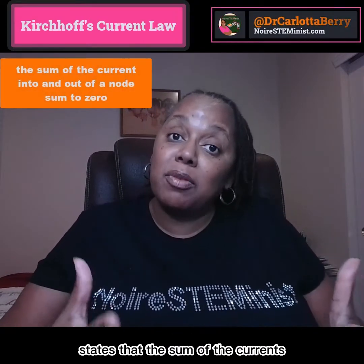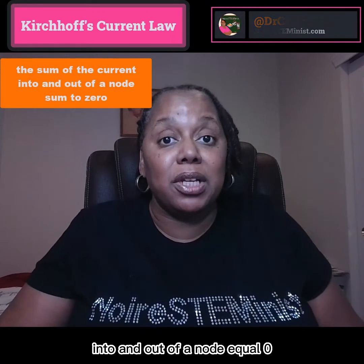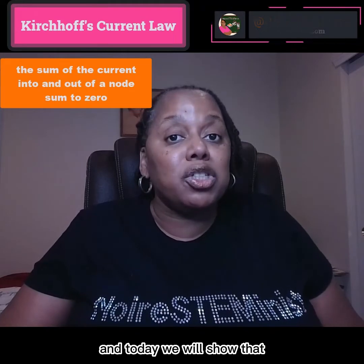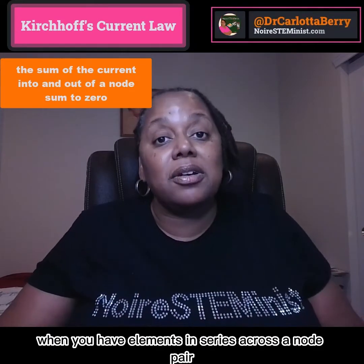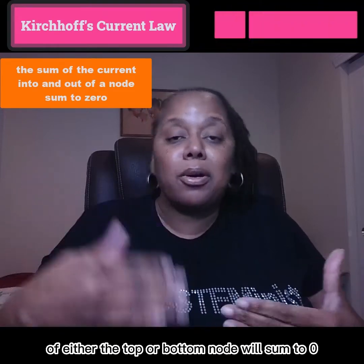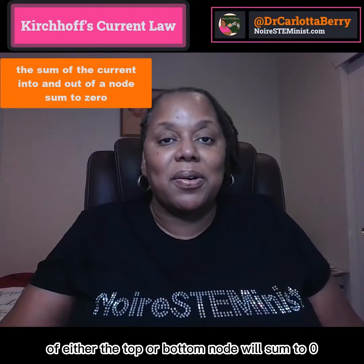Today we're going to talk about Kirchhoff's current law. Kirchhoff's current law states that the sum of the currents into and out of a node equals zero. Recall that a node is the meeting point of circuit elements, and today we will show that when you have elements in series across a node pair, the current into and out of either the top or bottom node will sum to zero. Come along and let's take a look at an example.